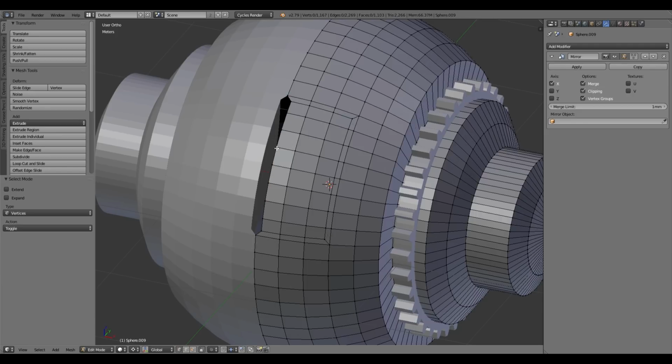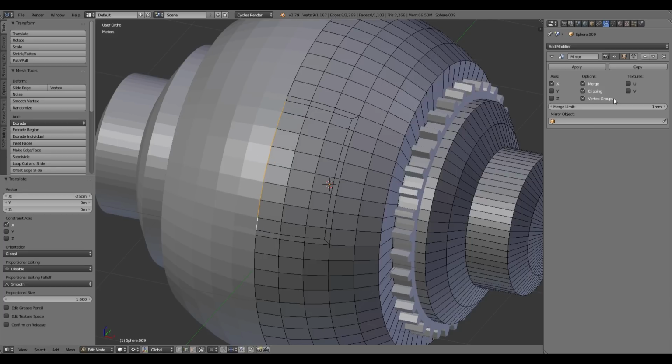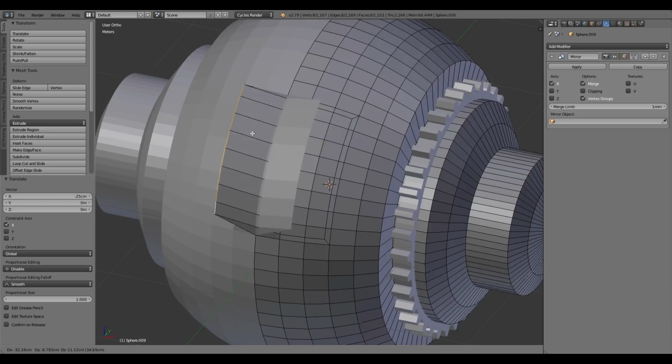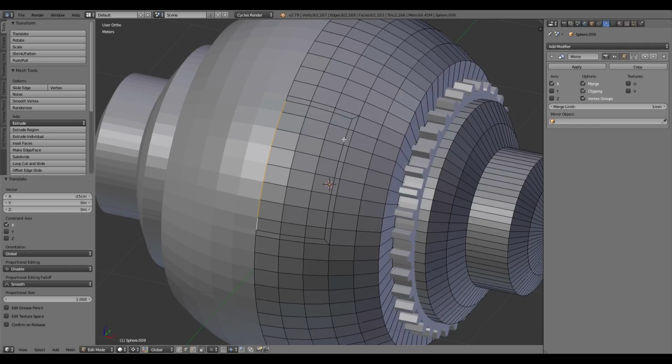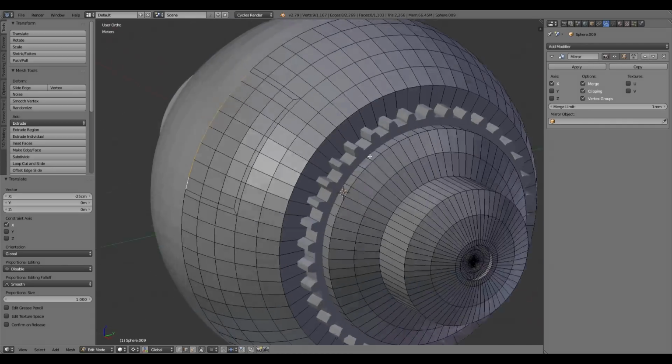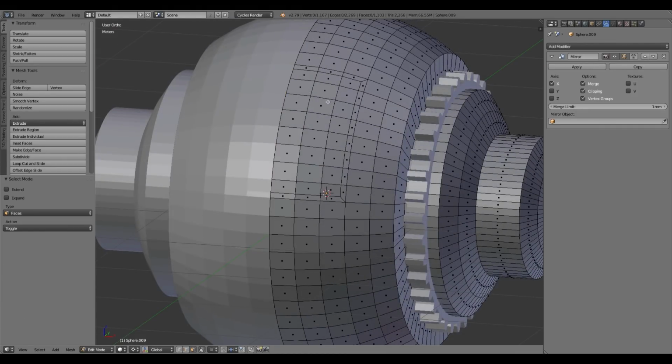Faces, go into edge select mode so that I can select all of these edges, just those, and when I grab them and constrain to the X, because I've got clipping enabled, okay, it stops at that median point. If clipping wasn't enabled, I can actually grab those and move them beyond that median line, and then you have to just basically estimate. So having clipping enabled means that everything along that center line mirrors perfectly and there's no overhanging information. All right, so now we've got those done.